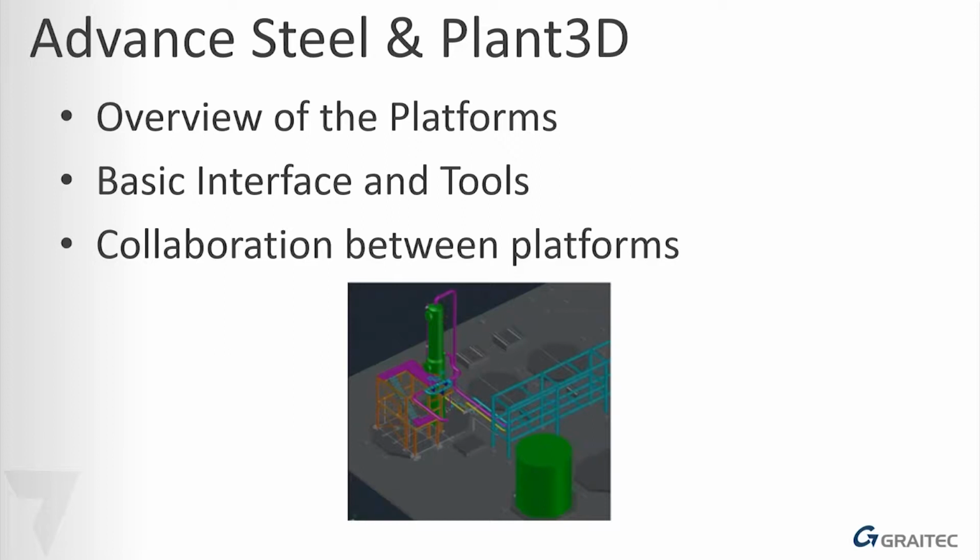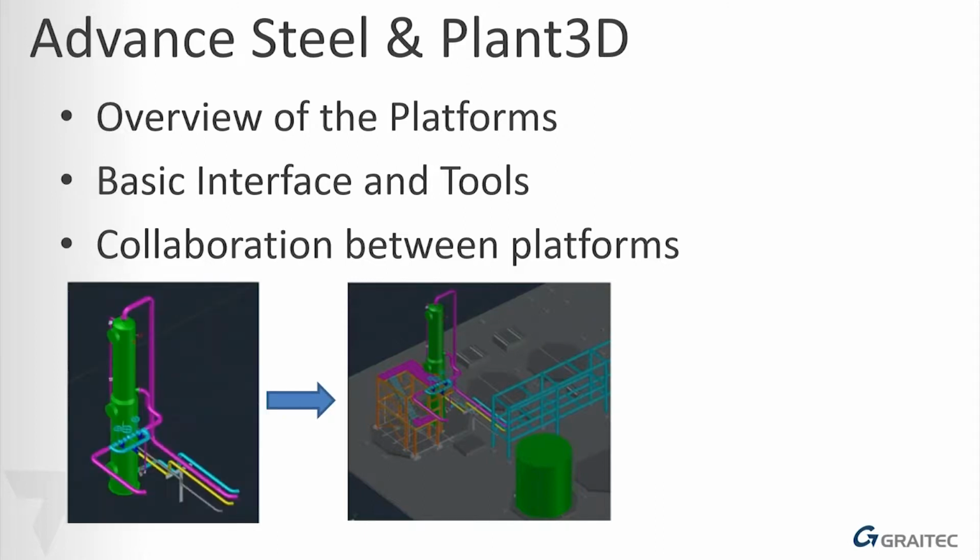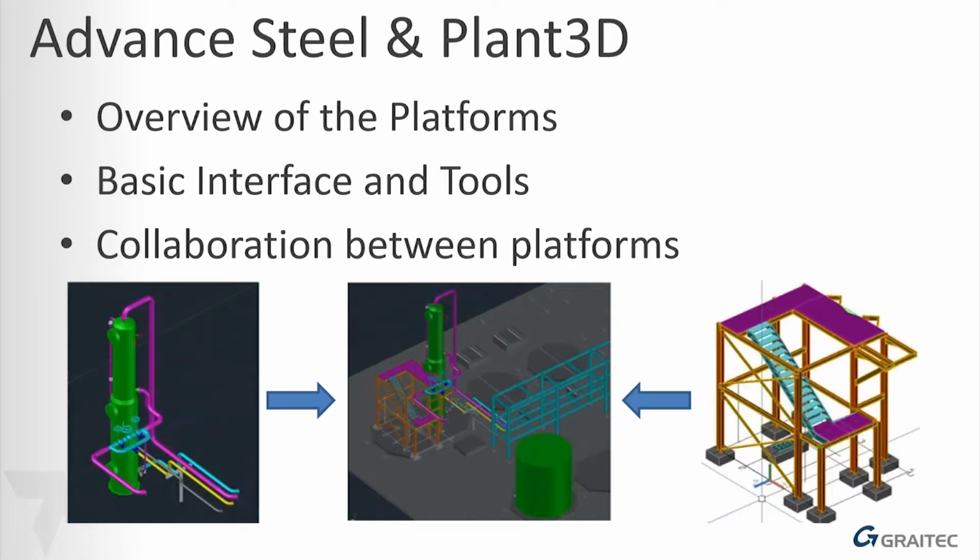Typically, most people use the plant project as the master file. Other things are subordinate to that. They use a series of X references, so they'll have various plant elements that are X reference files, and then they'll have a master file, which is the middle image. And then part of that is the steelwork. So the steelwork gets thrown in as a secondary consideration, and depending on what the design company or engineering service provider is doing depends on the level of detail that needs to be achieved.